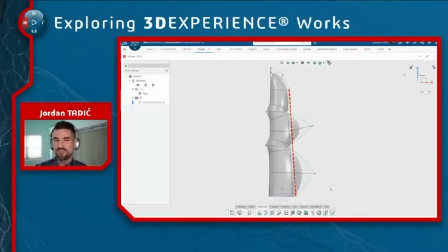Now, this is kind of a funky looking made-up scenario, but just to point something else out. And this isn't the best example that I chose here because we're doing this from the side view. If you're working from an orthogonal view, like the side, front, or top planes, then just use align by line in this scenario. But when you're working at a weird angle and you want a series of entities to be aligned in a theoretical line connecting the 2 points and everything else to fall within that line, then you're going to want to use the scenario that I'm showing right here.